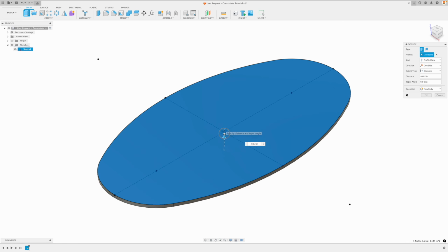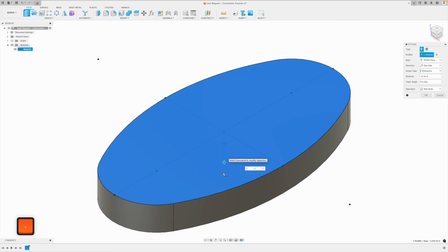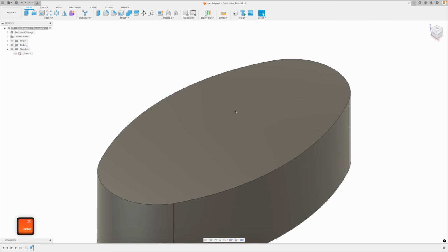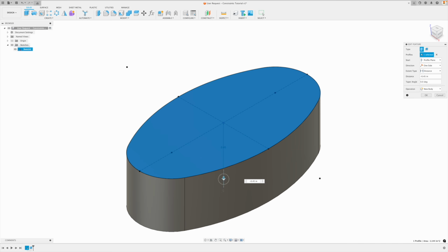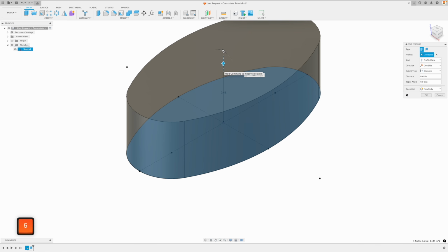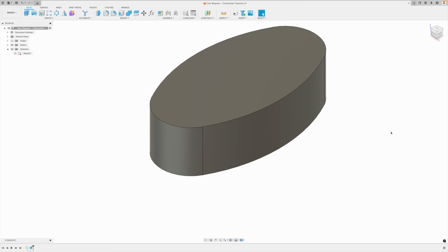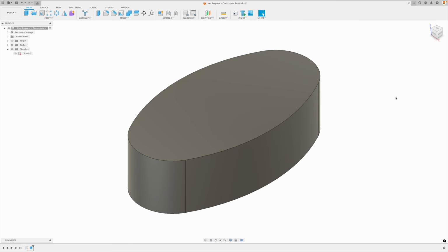Anyways, we're going to just drag this down. I'm going to type in the height minus 0.45. And here we're going to create the holes for the points, or the center points for our holes on this. Now, you might be asking, well, why did I go in the negative direction? How come I didn't go in the positive direction? Well, let's try that. Did you know that we can actually create everything in one sketch? And we're going to get back to constraints in a second.